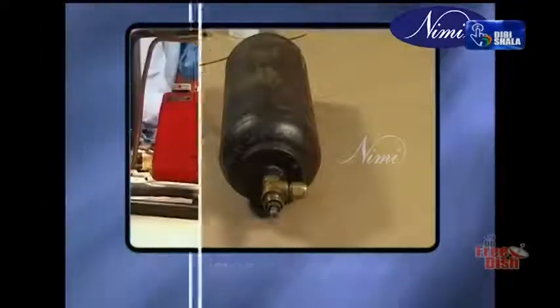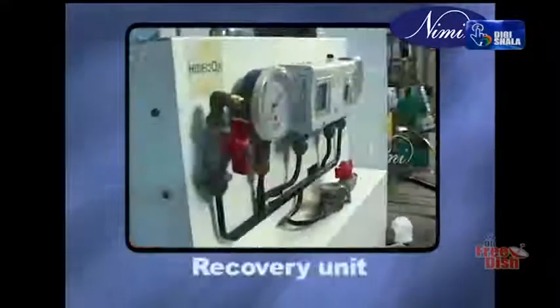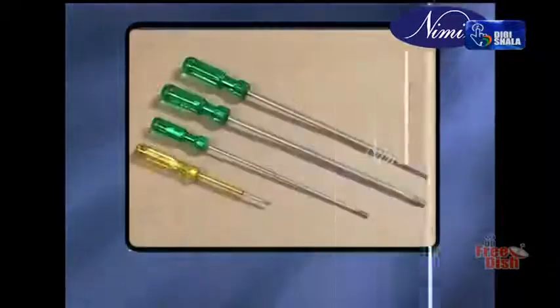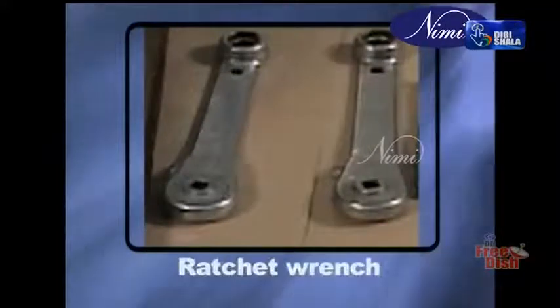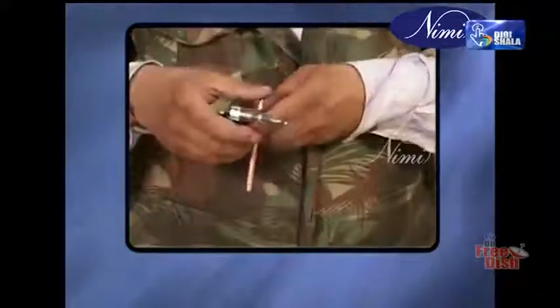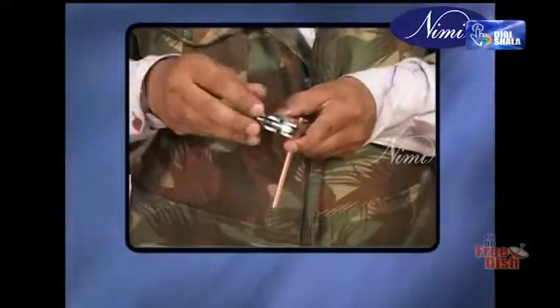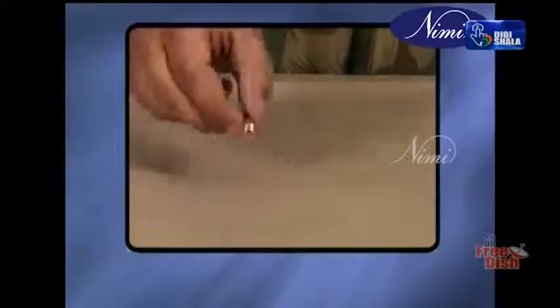Refrigerant cylinder. Vacuum pump. Recovery cylinder. Recovery unit. Pliers. Screwdriver. Spanner set. Ratchet wrench. Swagging tools. Swagging is a means of shaping copper tubing, accomplished with a punch type or screw type swaging tool. The tubing is clamped into the flaring block and a specially designed punch is hammered into the tubing, swaging or expanding the end so that it will fit over the end of another piece of tubing.